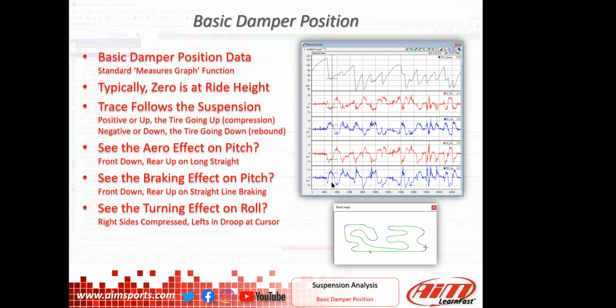As soon as the driver hits the brakes, of course, it transitions and transfers the weight to the front, and lifts up the back a little bit. So we can see that and how much that's doing it. It'll help us on maybe some compression damping or rebound for the back to keep the car a little bit more stable, the platform, if that's what's important to you.